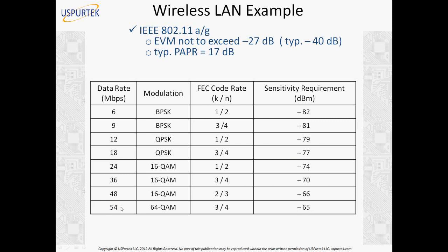Now let's pause for a while. So which one is correct? OFDM allows overlap of subcarriers causing significant adjacent channel interference. Cyclic prefix mitigates ISI. Tight synchronization is essential to avoid ICI. High PAPR can saturate amplifiers in OFDM receiver.